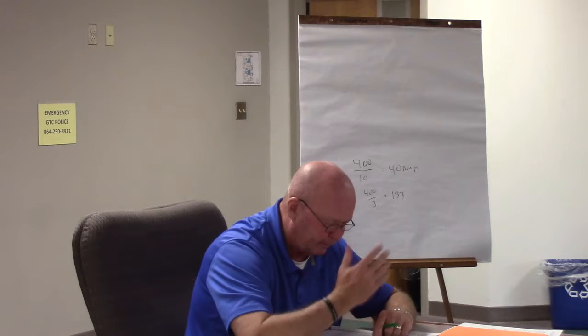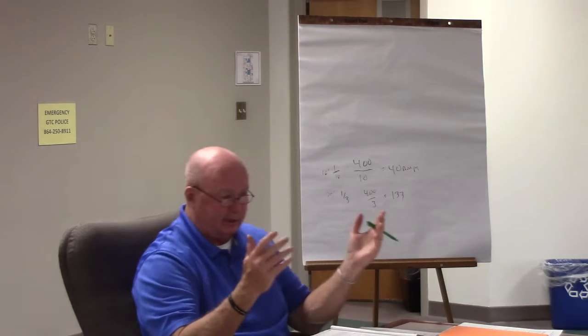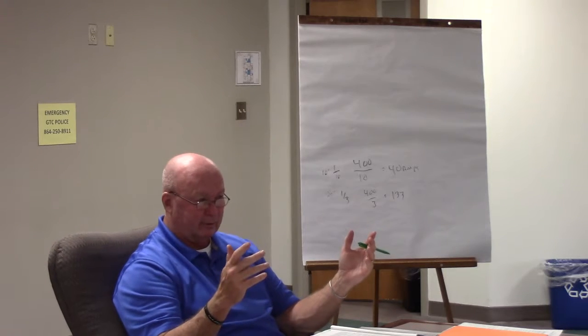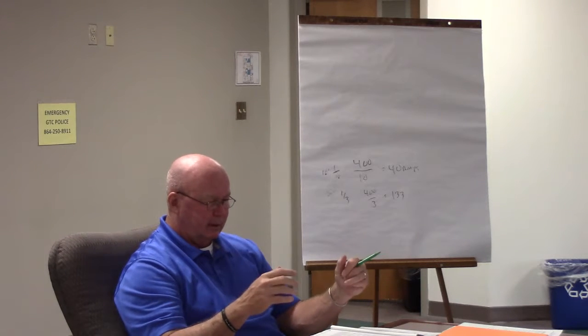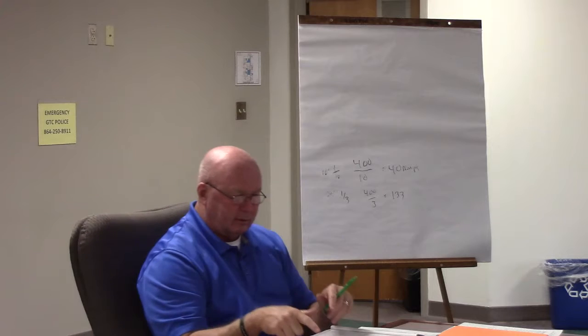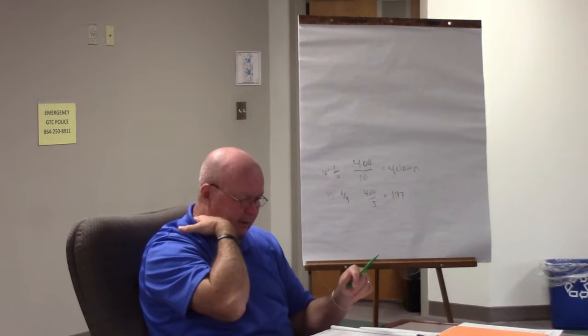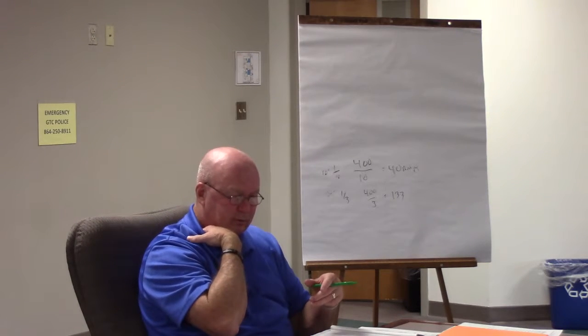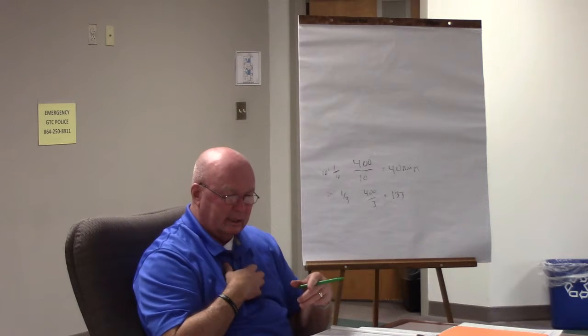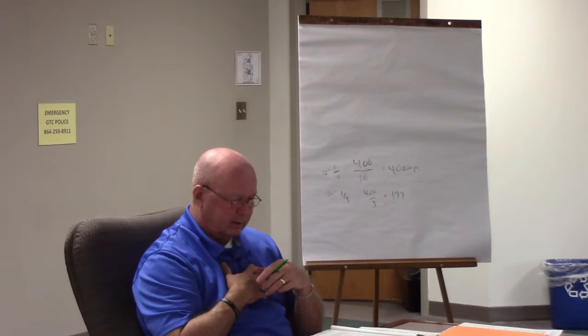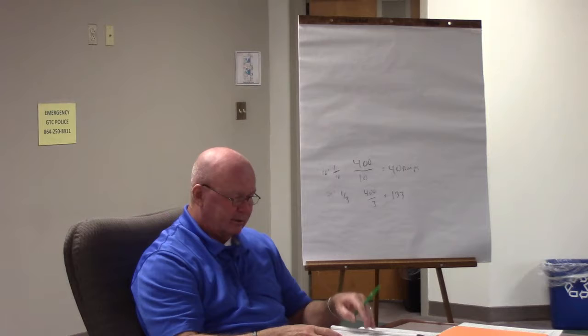And the last thing, the tap conductors must be enclosed in a raceway or otherwise suitably protected from physical damage. So let's just say it's in raceway, right? Now, y'all agree what it's going to be. So that's your 2 rules, 240.21. The first one is a 10-foot rule, number 2 is a 25-foot rule. Okay. All right, let's look at the next thing.